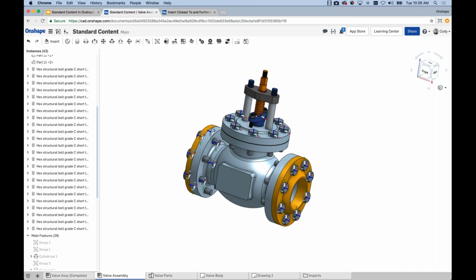If your surface has other holes, can you select a patterned hole feature? No. Very good question. So if your surface has other holes, in the example I gave you, I select the face and every hole in that face gets a piece of standard content. But what if you had multiple different size holes all on the same face? That's an example where I personally would select individual edges because you're right. There's no way today to select just holes of all the same size, at least that I'm aware of. So you just select a face and it grabs every hole in that face.